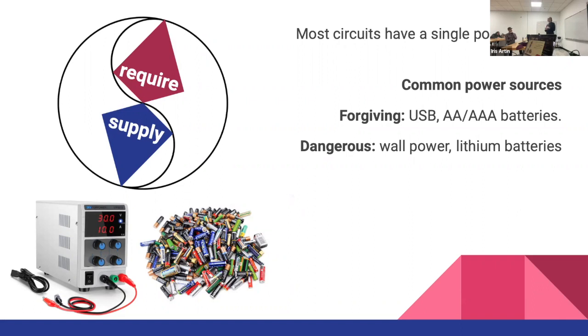But if the charger malfunctions and it puts too much energy in, then the battery can overheat and start a fire. And the thing that is particularly dangerous about lithium fires, and the reason why I don't think lithium batteries are a good idea for beginner projects, is that you cannot put out a lithium fire with water. It requires a special type of fire extinguisher, because the lithium does not need to be exposed to oxygen to continue burning.